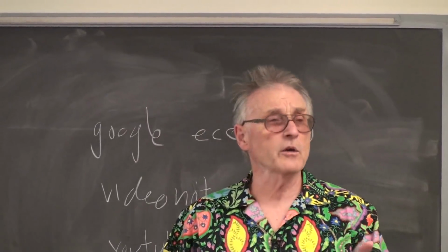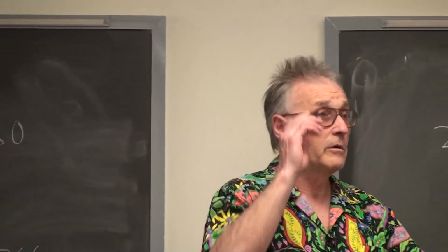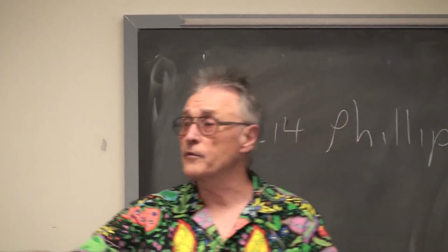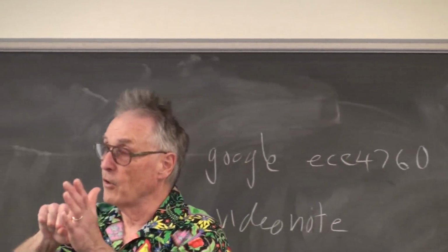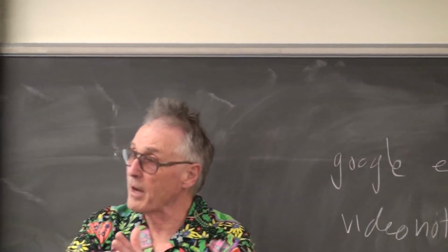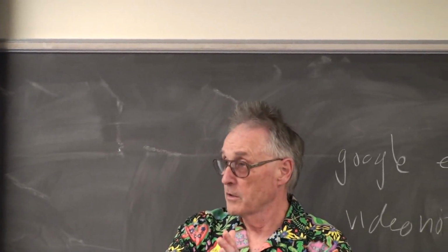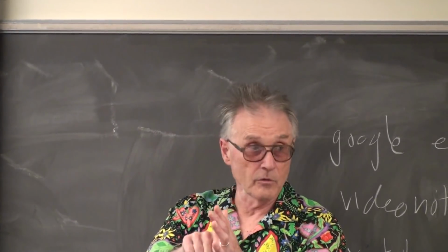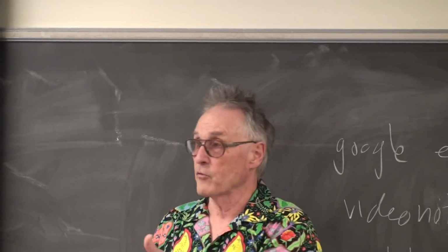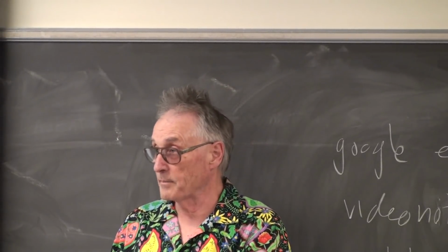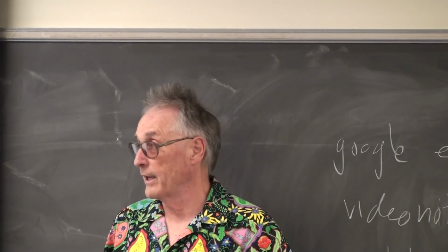So, yes, you can work at home. You can certainly program at home. You have the target board. You could, of course, for 10 minutes work, wire a 9-volt battery to run your board and skip the power supply, skip the 110-volt power supply. I have the mating plugs to plug 9-volt batteries into your target boards. That gives you a completely standalone system. You can program that directly off of your laptop. All you need then is a way of powering the peripherals, if any.